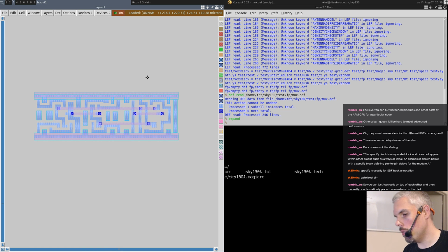And the first step is the global placement, I think it's called. It just looks at the connections and doesn't really care about the alignment or that kind of stuff. Cells might even be overlapping, so it's not a valid placement, but it gets a general idea of where things should be. Then it runs a second placement step called the detail placer, and the detail placer will move the cells to align them with the grid and make sure that they don't overlap with each other. That's kind of the placement process.